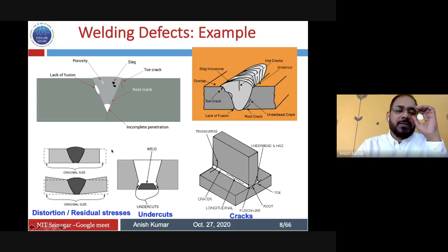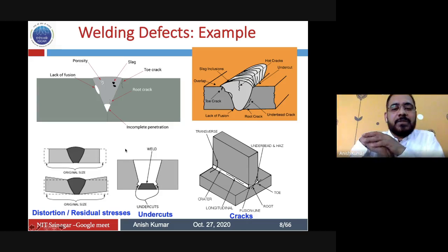with X-ray diffraction, but in many places X-ray diffraction cannot be taken to the surface. Then you have other techniques, like ultrasonic velocity measurement, that can be used for measuring the stress in the sample, or you can have magnetic Barkhausen emission, which can be utilized only on ferromagnetic material, but that can also give you an idea about the stress that is present in the material.